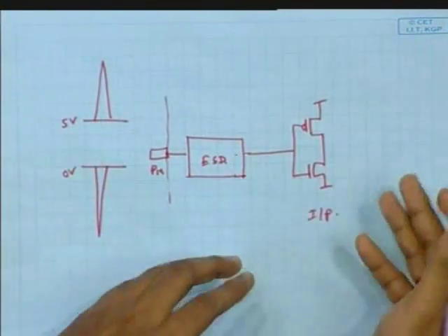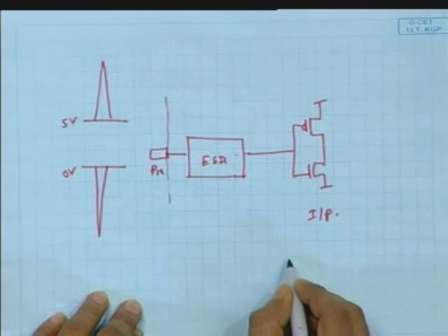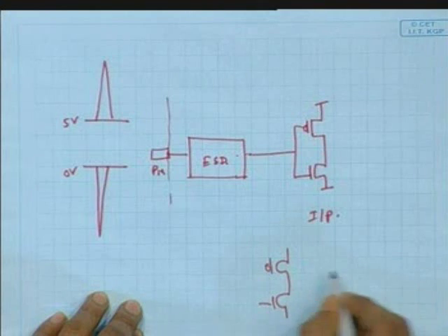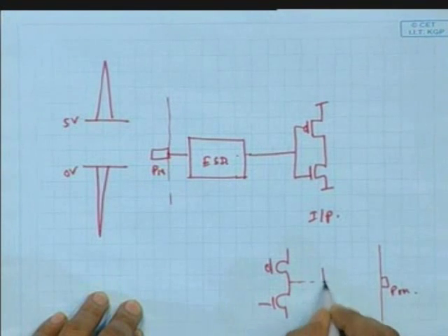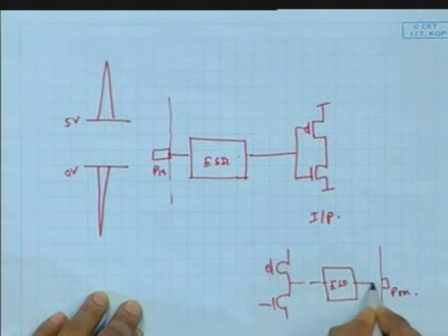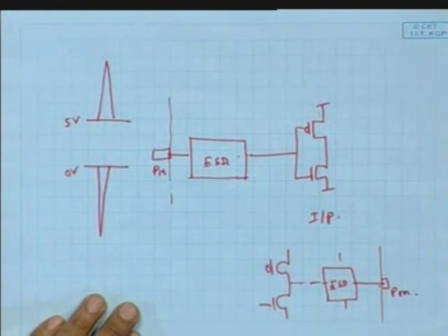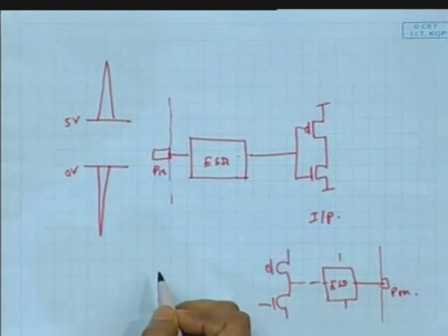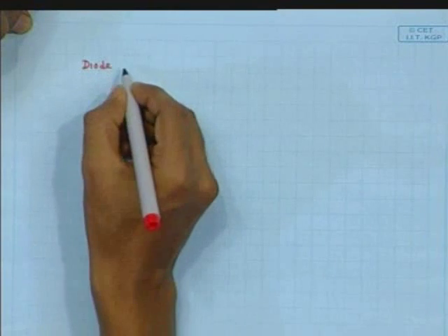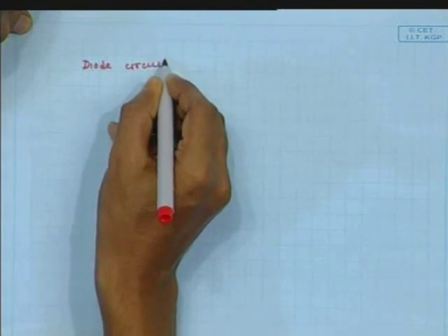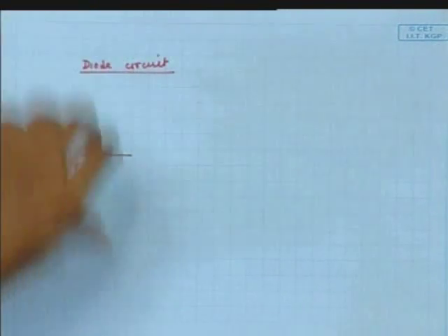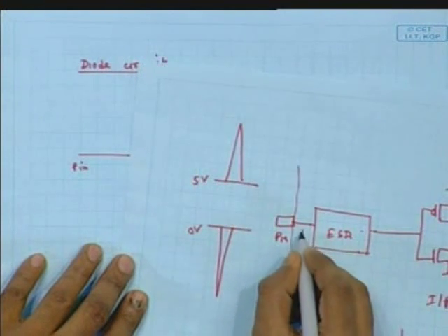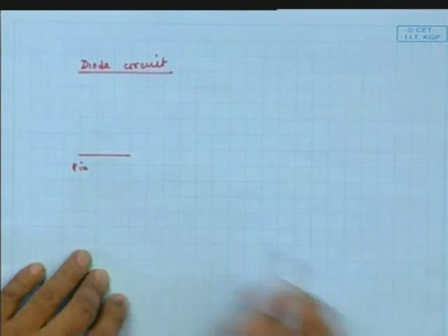The same thing will be there at the output side. Consider this is a simple inverter output buffer. This is the pin. Okay. So some ESD circuit will be here. Now consider what is there for this. The very standard one is the diode circuit model. So this is the pin signal. We consider this is I, this is O.